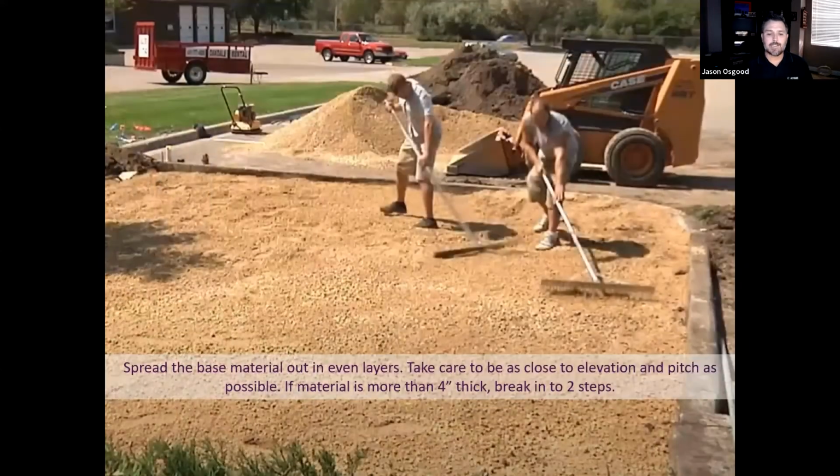But once you get it onto your deck area, you're going to want to spread the base material out as evenly as possible. Take care to stay as close to your elevation and your pitch as possible. Keep in mind that this material will compact differently in different spots. You might have a little heavier aggregate in some spots and a little lighter aggregate in other spots.